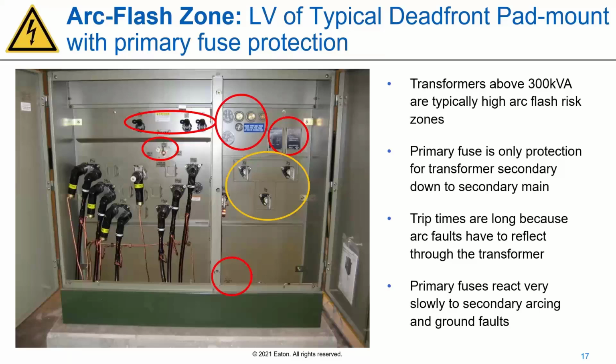And some people may think, why would I even need to get into the transformer secondary compartment? You know, there are solutions like putting the gauges or nameplates and things like that on the outside of the compartment. And I wouldn't argue with that. Removing people from that arc flash zone is always a great solution. And it's also obviously a cheap solution as well.